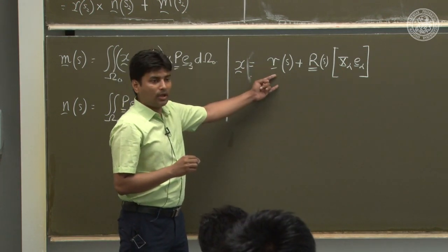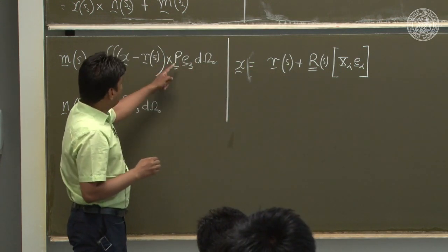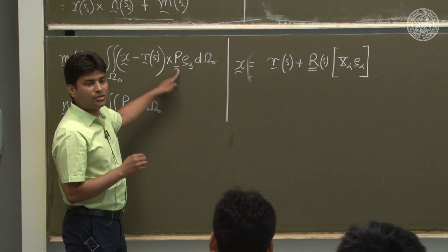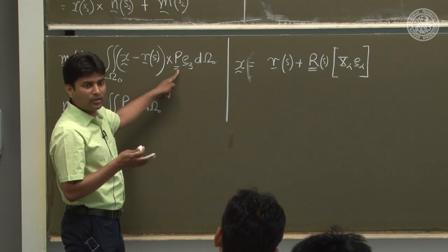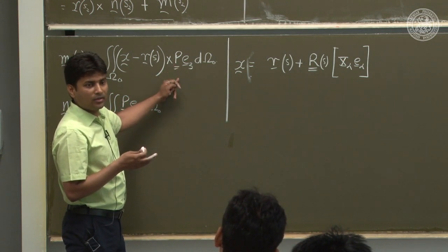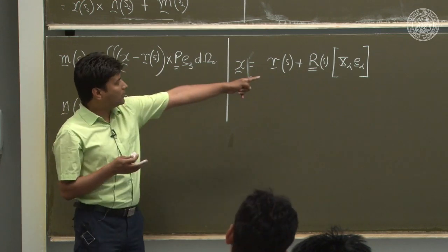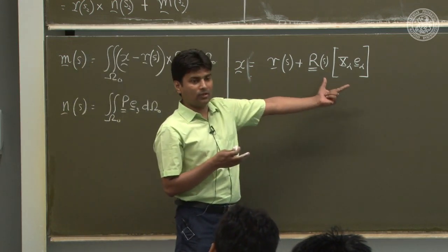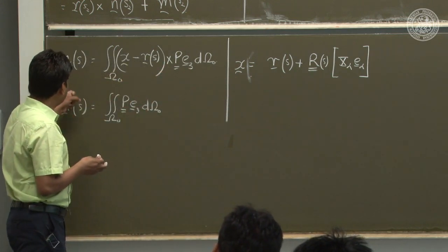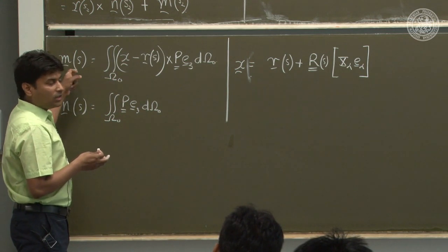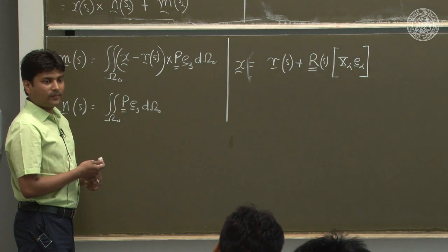Use this deformation map, take the deformation gradient, and get your P from the 3D constitutive law. P is equal to del W over del F if it's a hyperelastic material. And here this simply becomes big R times x alpha E alpha. So you can directly get your forces and moments in terms of the kinematic variable, isn't it?